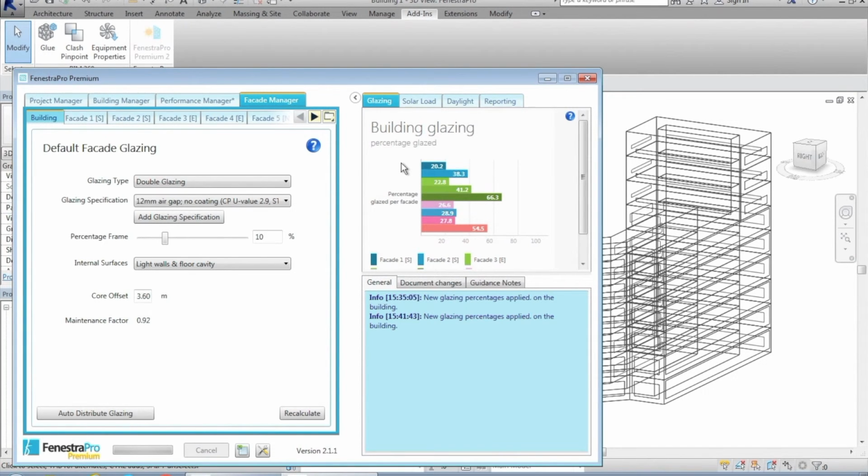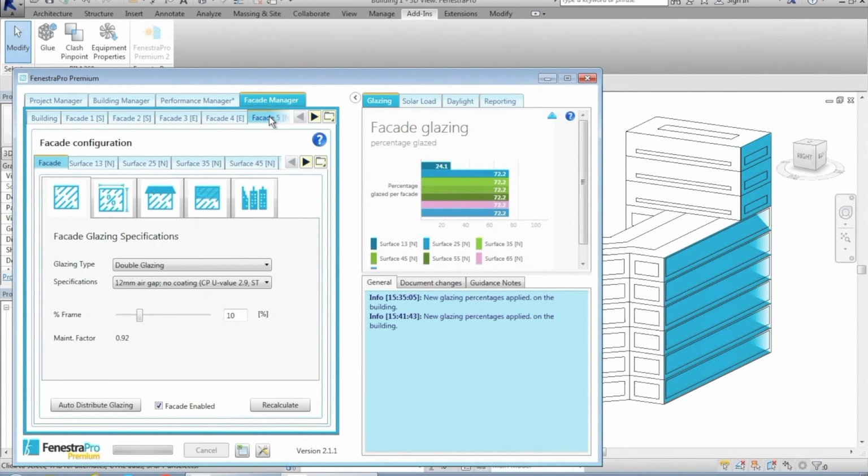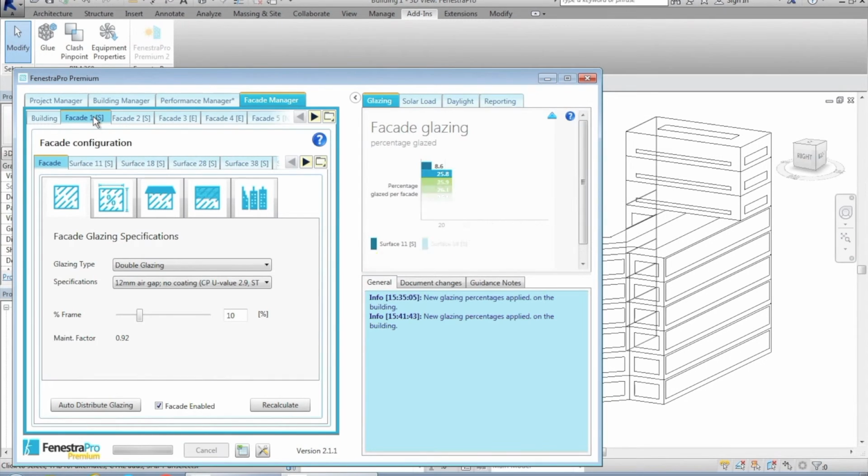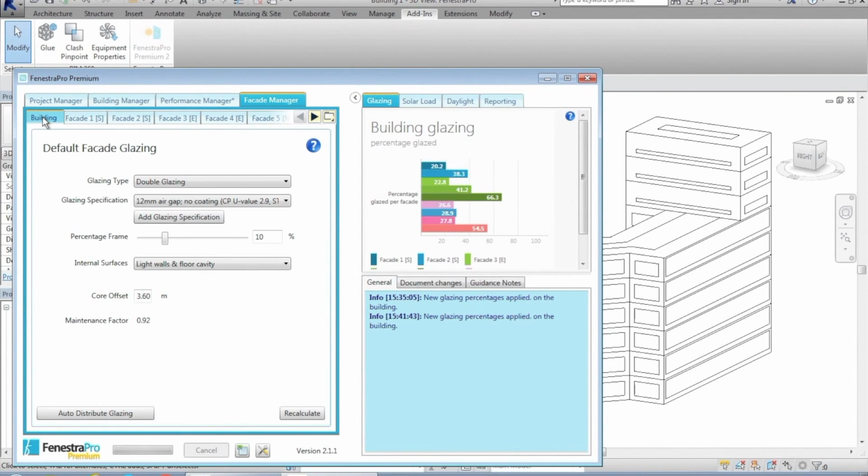So in other words, on the north facade, for example, there is over 80% glazing. The south facades are down to 30% glazing, and then the appropriate heat gains. So now we are at a point that we can start manipulating these heat gains and trying to manage that overheat and bring that overheating level down to a more comfortable 25 watts per square meter.